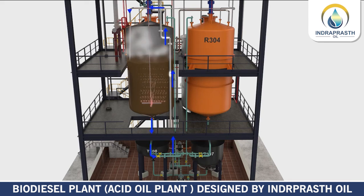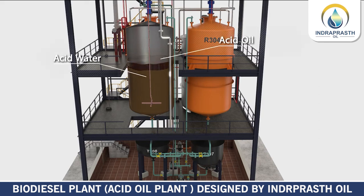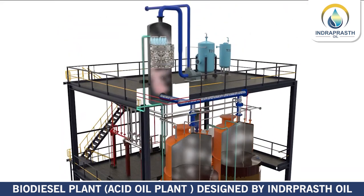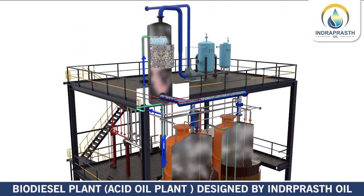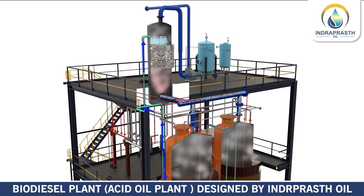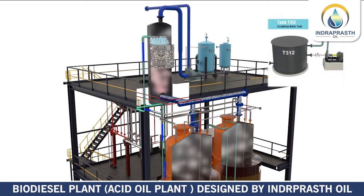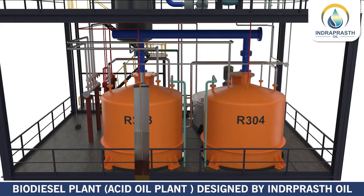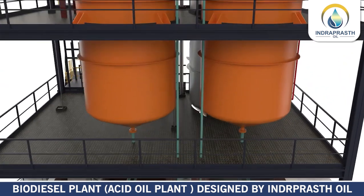After homogenization by recirculation for 60 minutes, the mass is allowed to settle. The mass settles into two layers, the top layer of acid oil and the bottom layer of acid water. The acidic fumes generated in the reactor are taken to the vapor scrubber VS311, where water is in continuous circulation. When the water becomes enriched with acid, it is drained into the acid water tank T307. The two layers formed in the reactor are separated by gravity.